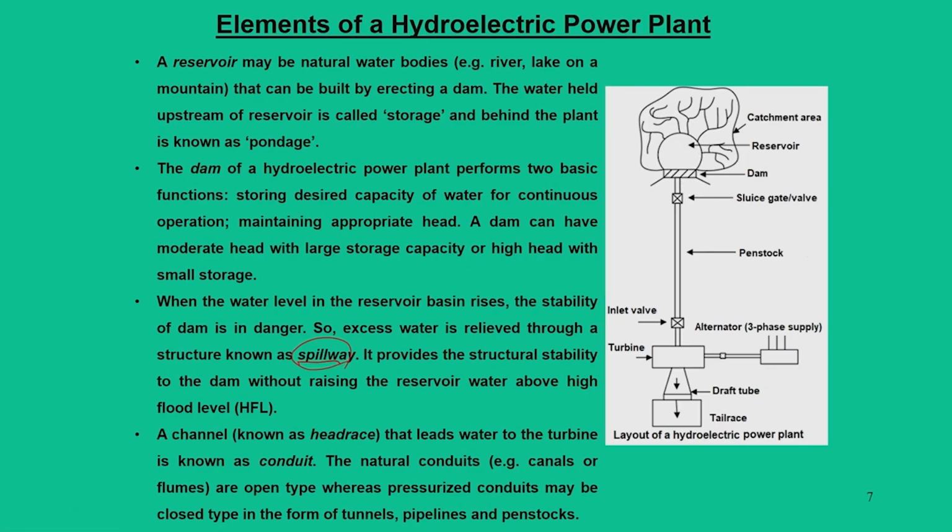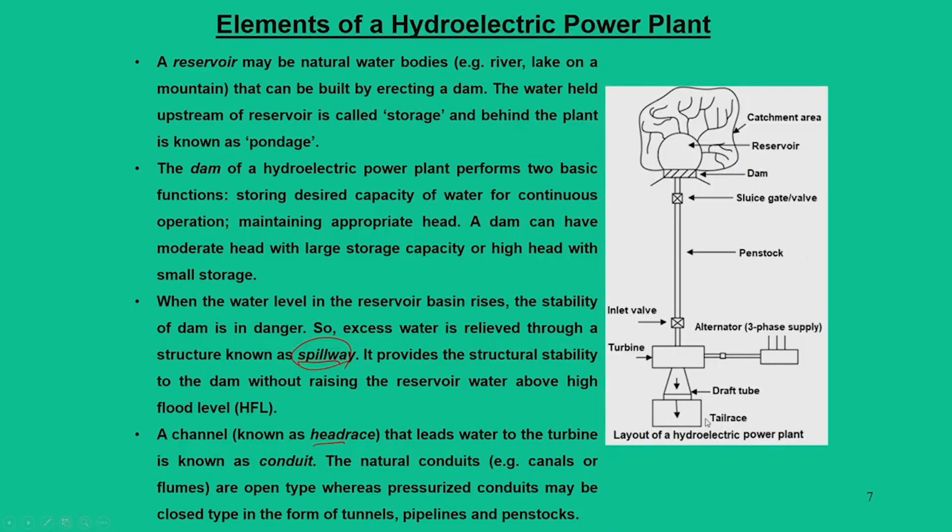The other option is that we can open up this penstock. That means we can think of the penstock as an open channel flow from the reservoir end to the turbine, by assigning a suitable slope for the passage of water. This channel has two components, the head race and the tail race. In that case, the entire flow through this open channel is almost atmospheric. So that is another possibility for the passage of water from the reservoir to the turbine end.